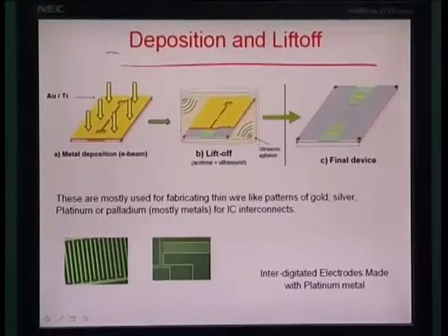Okay, so after doing these sputtering methods, let us briefly discuss what the e-beam evaporation, the vacuum evaporation or sputtering can be used for. So, the best way of using them in microelectronics or MEMS is deposition and liftoff, wherein basically metal circuits or metal conduits are fitted within or over a sacrificial mask made up of positive tone resists.